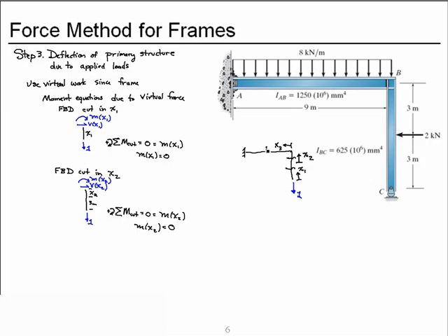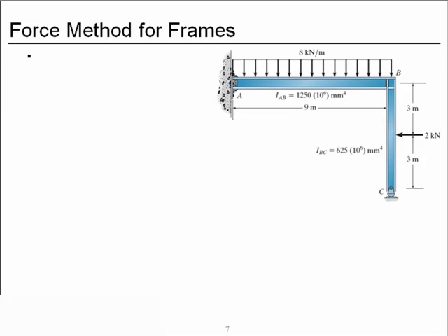Next, let's cut it in the range of x3 and draw a new free body. So I draw a free body diagram of the section cut in the range of x3, and I'll keep the right piece. It is 6 meters tall, x3 long. We have our virtual load applied here, our unknown shear as a function of x3, and our unknown moment as a function of x3.